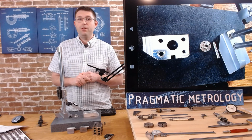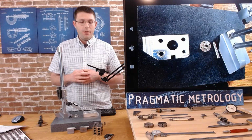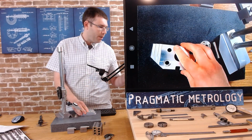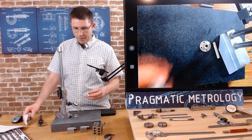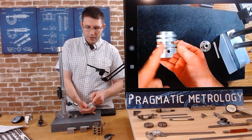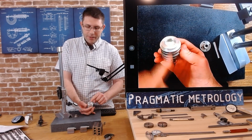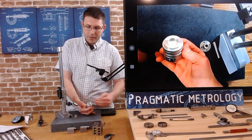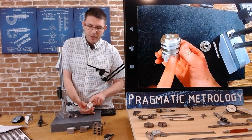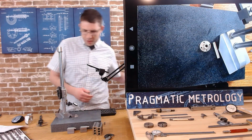We don't often see a position called out relative to just one datum, but the best example I could think of is this. If I have this part here and I needed a slot along the side, some sort of milled slot, and I want it center line to the axis, I don't want it off center in this direction, and I don't want it twisted, you may call a single datum to control that. So let me try to draw that.